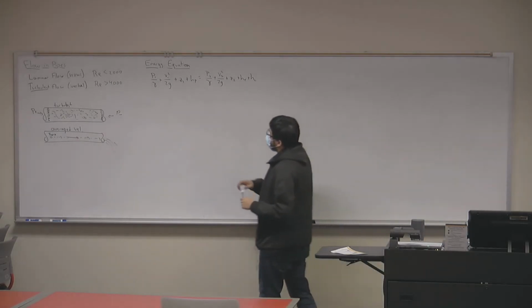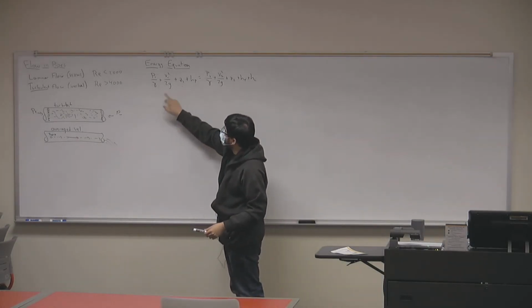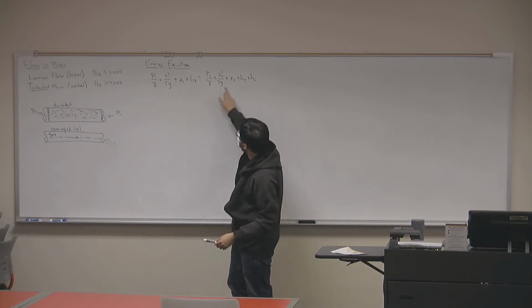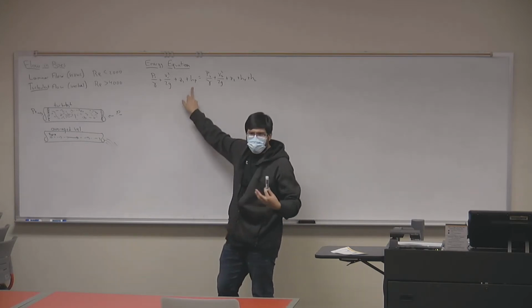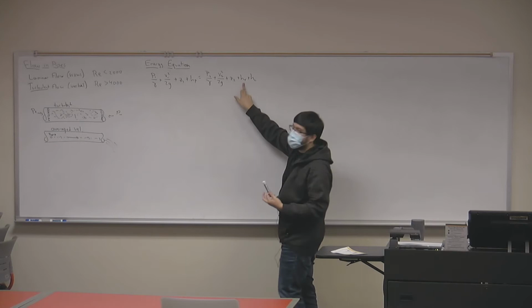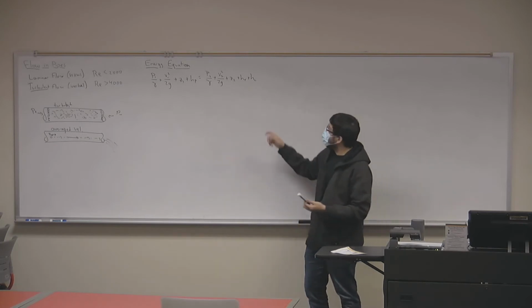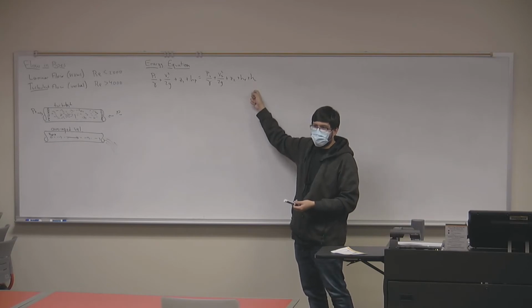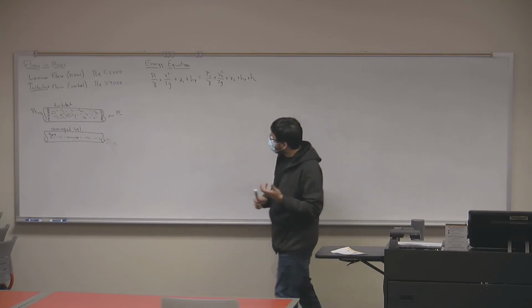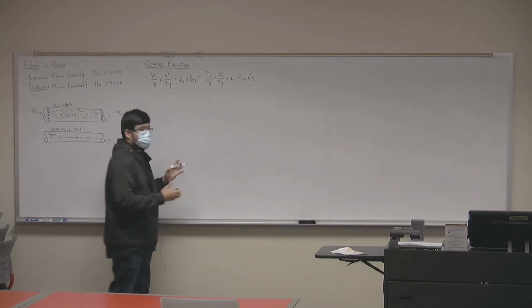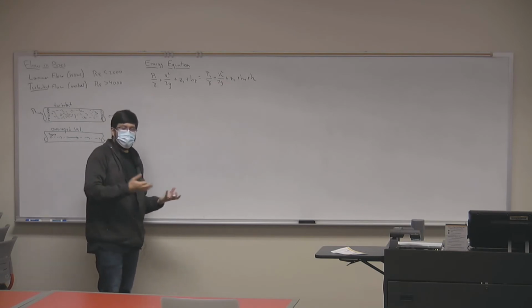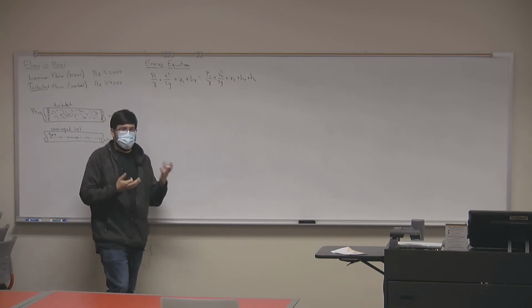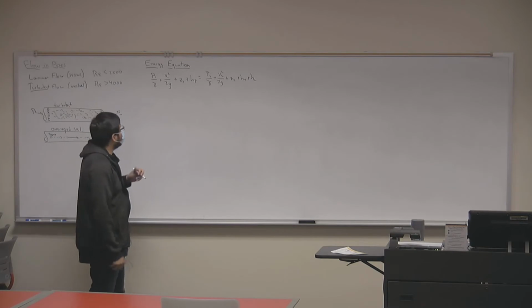Now, when we studied the energy equation, we mentioned that we have our energy terms: pressure, kinetic, potential. We had pump head, which was energy added to a system. We had turbine head, which was energy removed from a system. And we have this HL term. Do you remember what this HL term was? Head loss, right? And head losses were energy that was lost through heat transfer, friction, and other changes in energy.